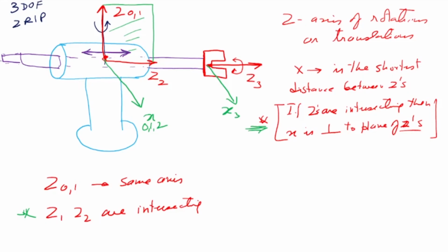Now I can write the DH parameter table of this one. Let me say that theta1 is the variable here. This distance, which is a variable here, is d2, and theta3 is the variable there. d2 is the translating variable. And there is a distance, let me say, from here to here, which is L2. I hope you can imagine that. Now please note that Z0 and Z1 are on link 1.